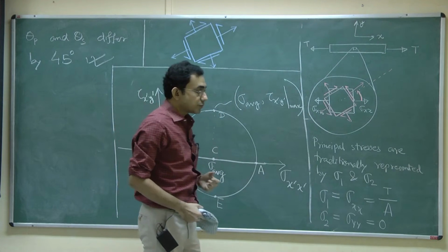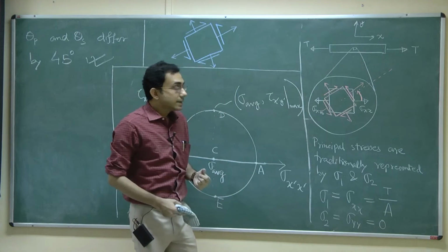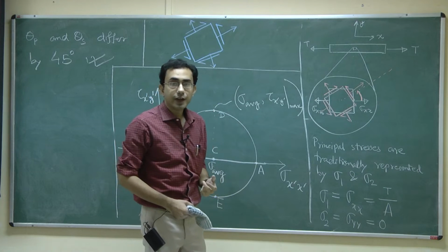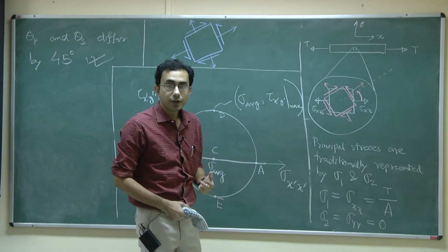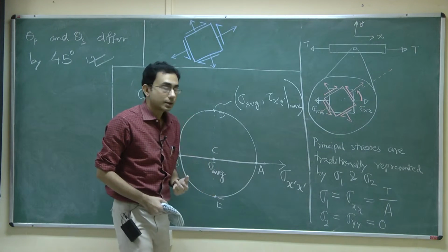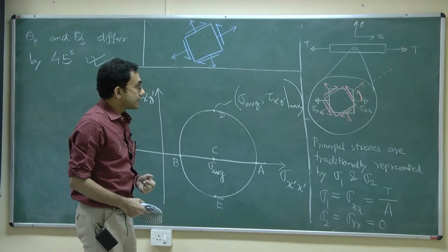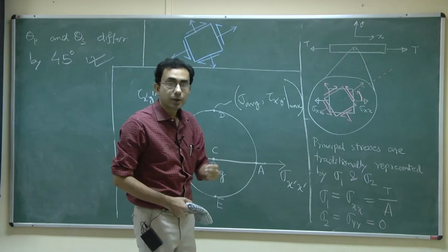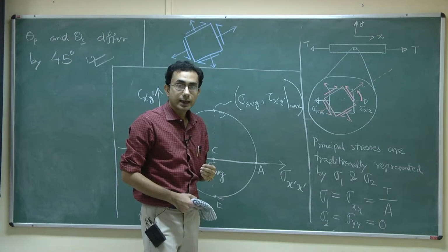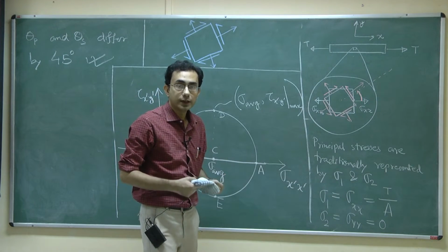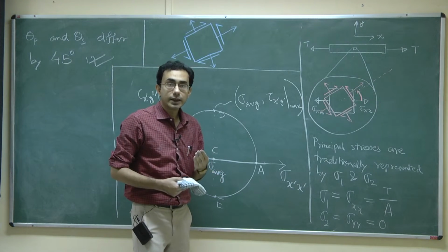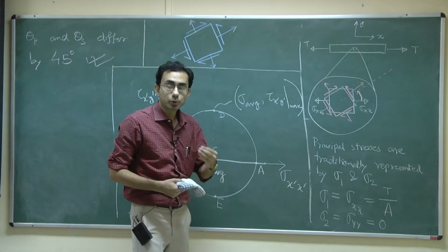Now, it has been experimentally found that these ductile materials, you will often find this statement made in textbooks that they fail in shear, that they are very prone to shear stresses. What this means is that whenever at those planes where you have the maximum value of the shear stresses, they are most susceptible to failure.